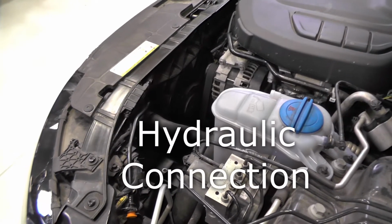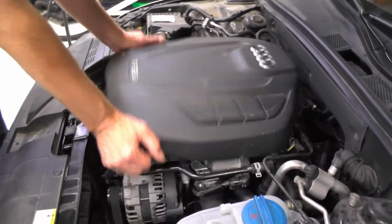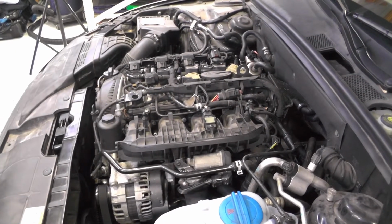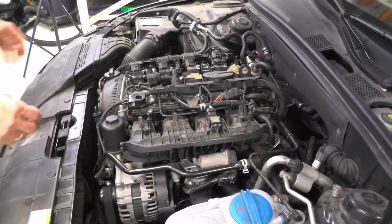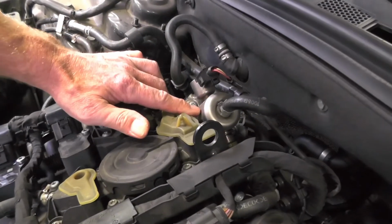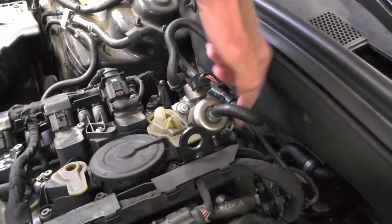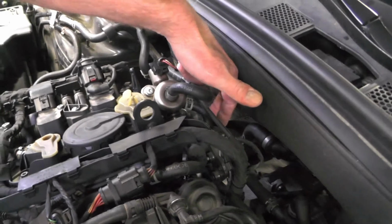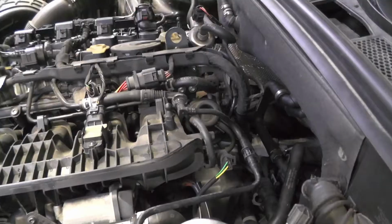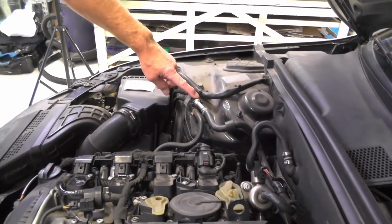Next, we will look for the hydraulic connection where we connect into the supply line. So I remove this cover to better see what we are looking at. We can see the high pressure pump over here. It's a GDI piston pump, mechanically driven. And it has back here the high pressure metal line that goes out over here. Then it has the supply line coming from top, connecting over here.